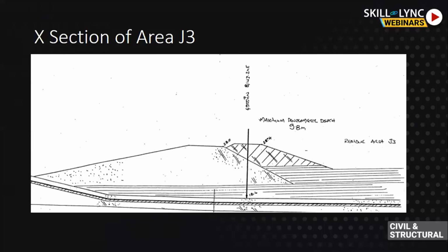In addition, by observation, the J3 embankment performance was inferior to J1 because of trafficability. J1 performed better, with adequate access for two-wheel drive vehicles, whereas J3 required all-wheel drive vehicle capability for access. And in the case of J3, the soil was a little loose on the surface, and it was more prone to dust production and more susceptible to re-wetting with the rain.